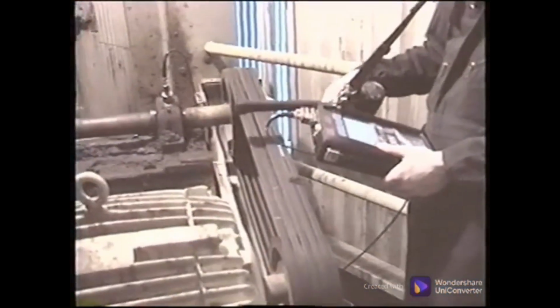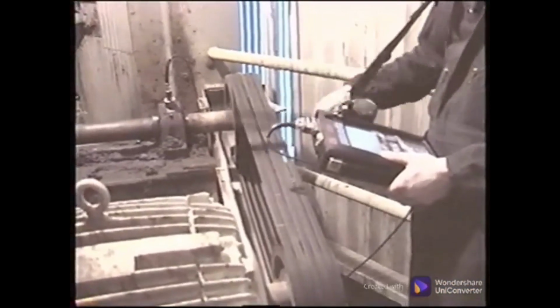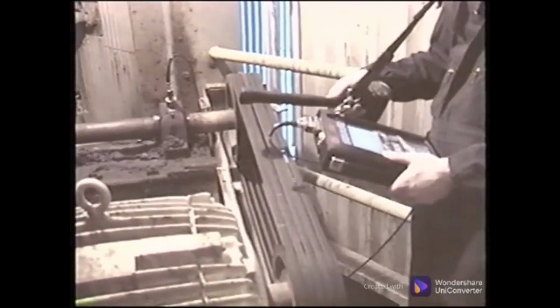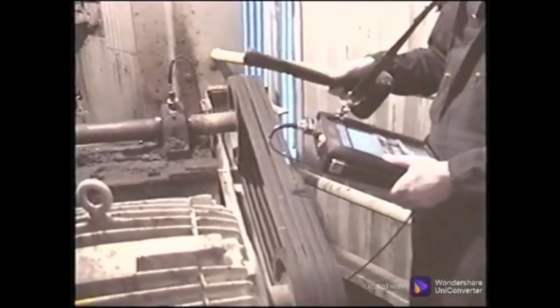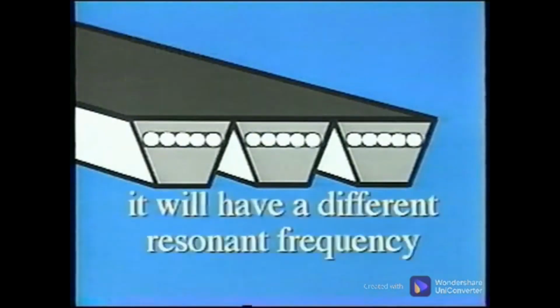A very real danger exists when the belt strand resonance is near another primary frequency, such as a shaft turning speed or a system resonance. The two frequencies may generate a beat which can be high enough to destroy the machine. A solution to this problem is to replace multiple V-belts with a single banded belt, which will have a different resonant frequency and may move it away from the other frequencies.